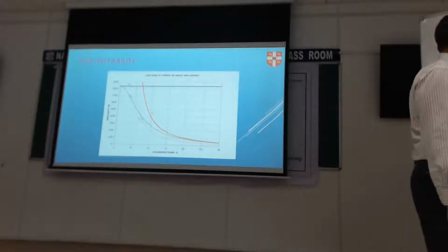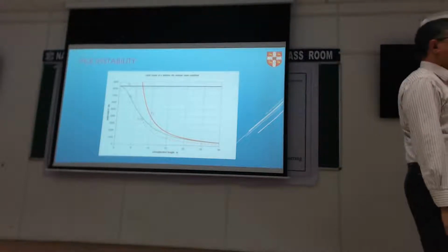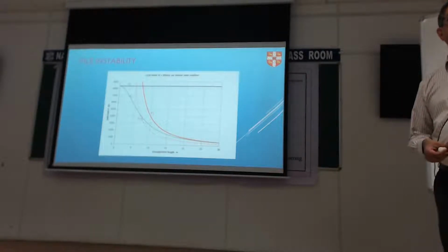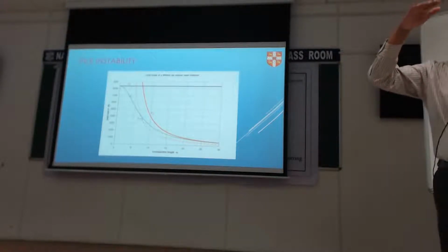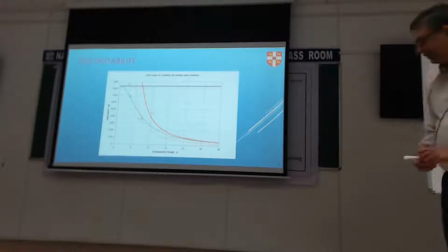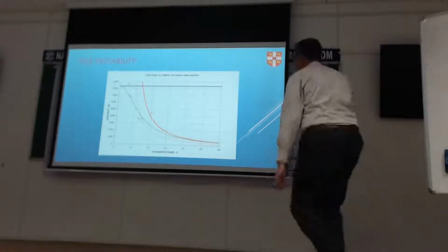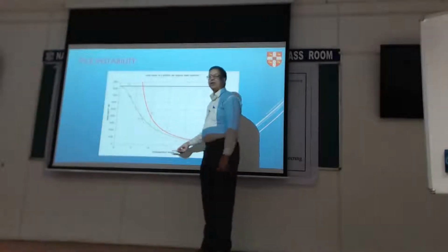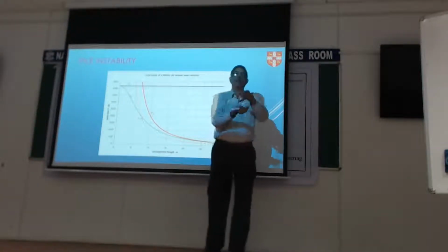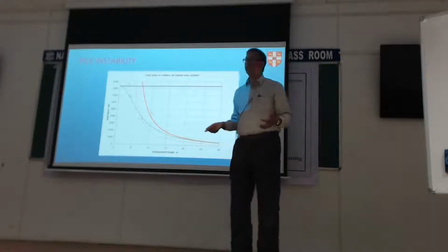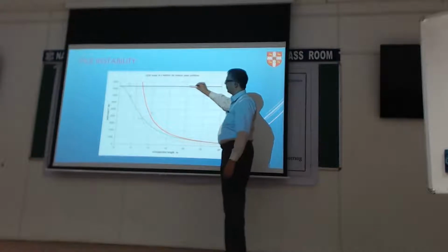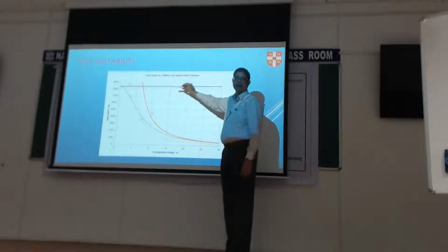However, just because of the material, you'll have some limit on the yield of the material. That is marked by this blue line. It does not change depending on the unsupported length. Every element gets compressed and it can reach yield in compression, right? So that marks the top limit of what the material can take.